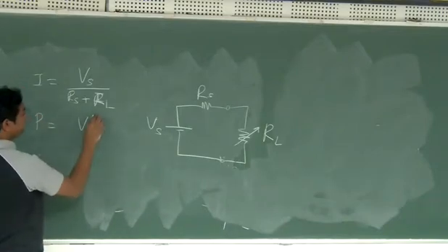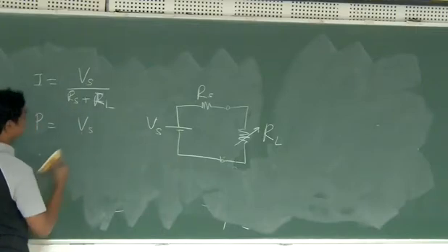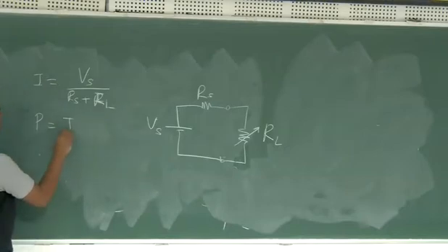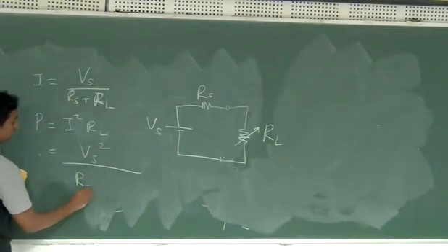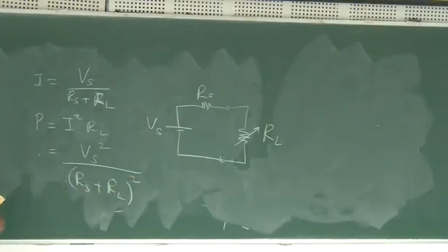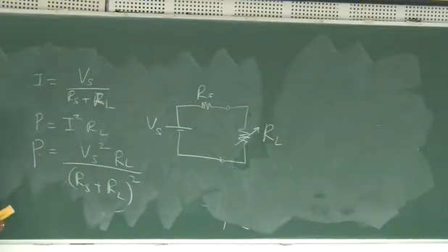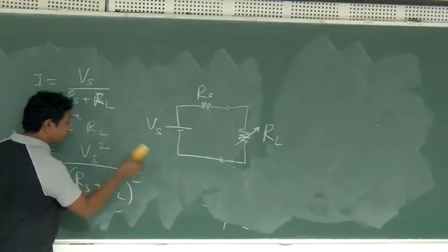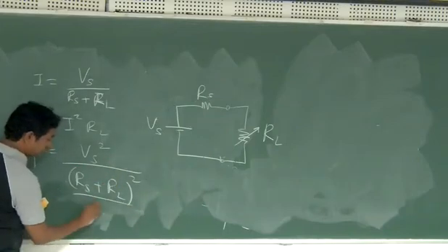Okay. So that will be VS. So sorry, what is power? So power is I square RL. Okay, the square of this. So VS square divided by Rs plus RL whole square, isn't it? Into RL in the numerator, correct. Okay, so this is power. Okay, so a small manipulation, just RL you take it to the denominator. Okay, so it will be again like this.